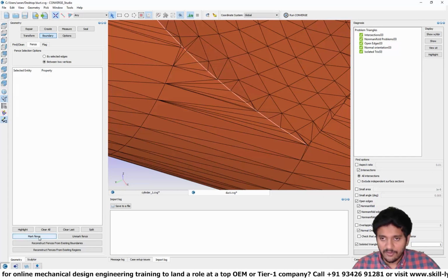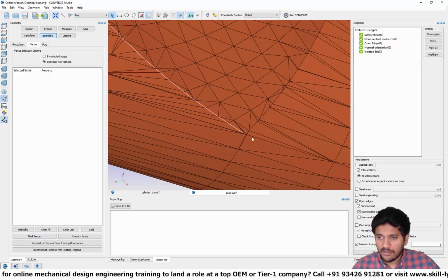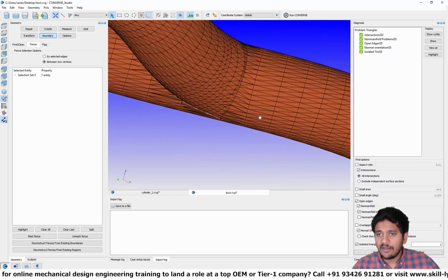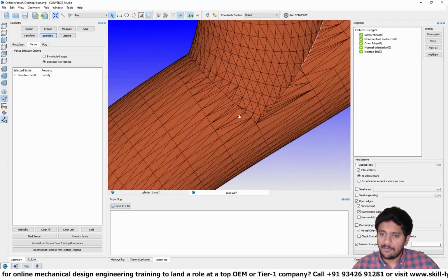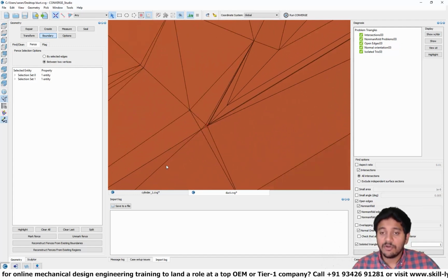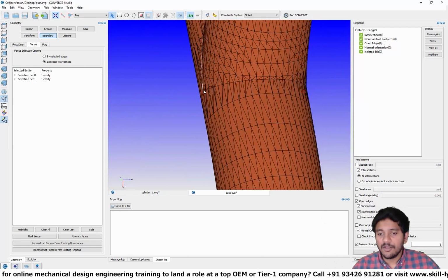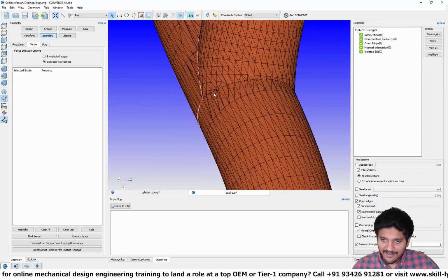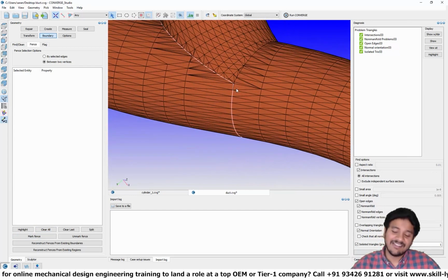So let me click on mark fence, and there you go. It seemed to work correctly. Now the next fence that I want to create is going to start at this point. Let's try to maybe rotate the geometry, and I'm being a bit ambitious here. I'm saying, okay, try to create a fence from here to here. Obviously, it's basically like telling CONVERGE, okay, you're at this point, go to that point, and we're expecting that it's going to take this particular path. So let's click on mark fence, right? You see that it did do that, but it went in the other direction.